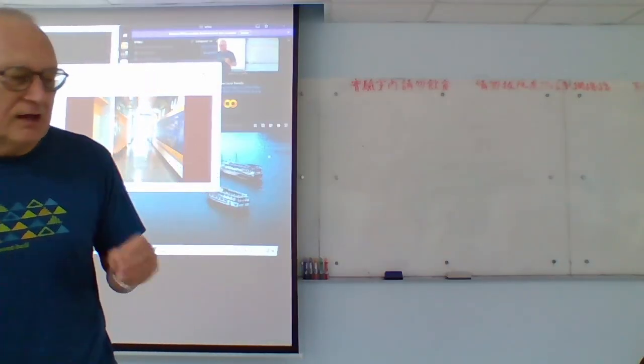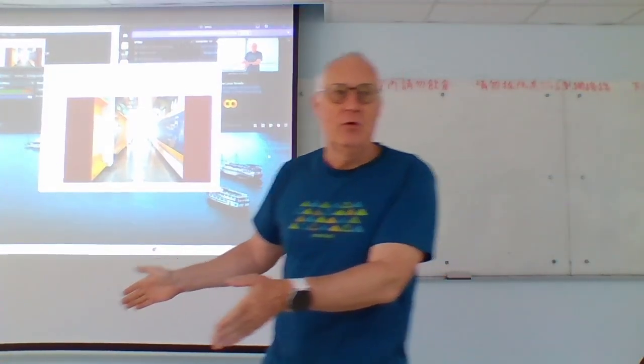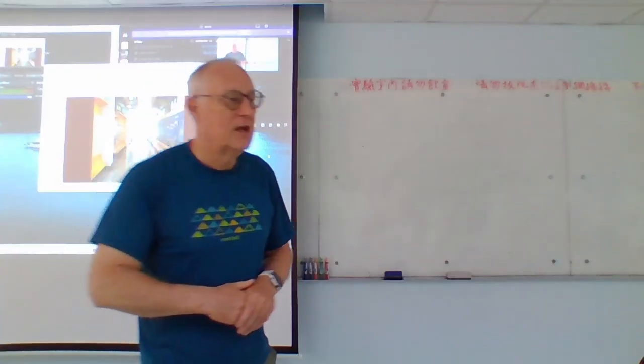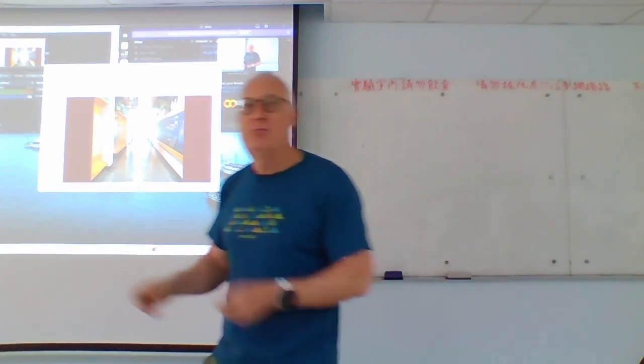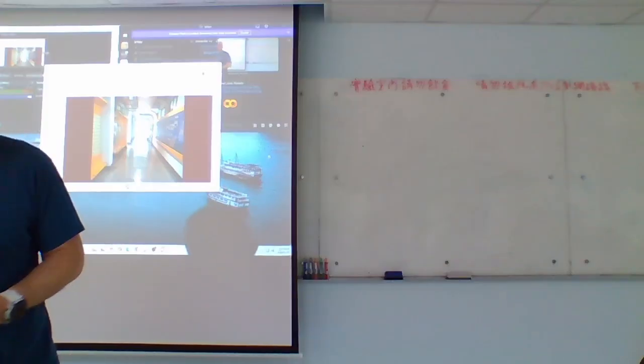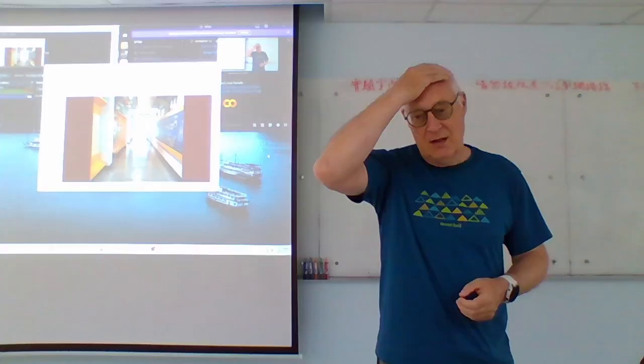So this kind of mapping that we want to do, the problem of taking a local snapshot of the environment, moving a little bit, localizing yourself within that snapshot that you just took, and now you can see a little bit more. That's called simultaneous localization and mapping. Localization is finding your position in a map. Mapping is building the map of your environment, the global map. Simultaneous means that we're doing both at the same time. Right? Localization, then mapping, localization, then mapping.